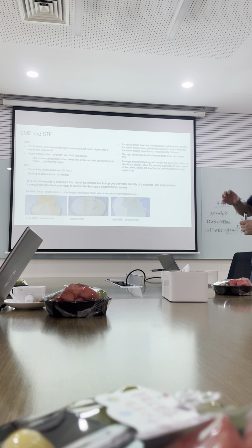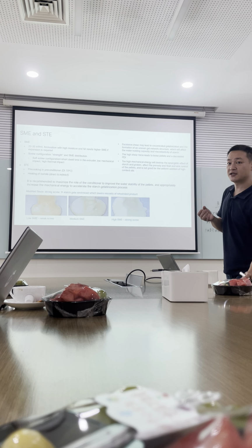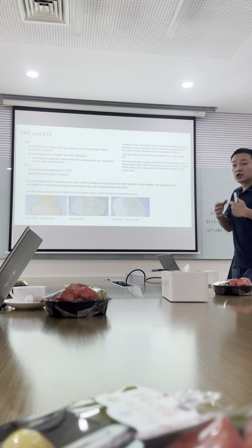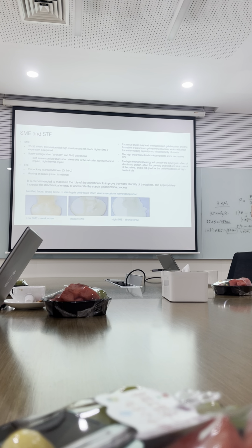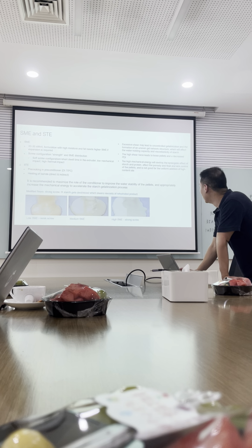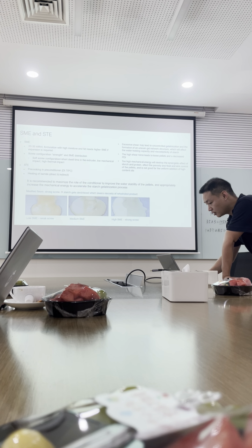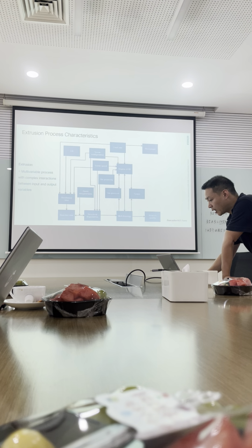Because starch with too strong shearing force gets dextrinized. That is not good for digestibility, because animals can't easily digest the dextrinized starch. So we also need to care that the SME should not be too high, otherwise the nutrition is not good.